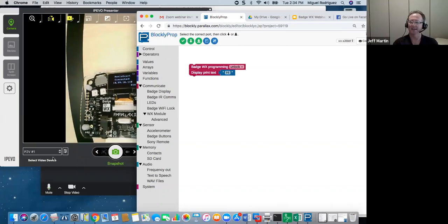When the batteries get low, strange things sometimes happen. Maybe you'll be associated with an access point and things look fine, but you start having download errors, like communication failures in midstream, where you'll see an error message on the screen with Blockly Prop, but you won't know exactly what's causing it. Oftentimes, switching to fresh batteries will solve that. I'm not sure if that's what's happening here.